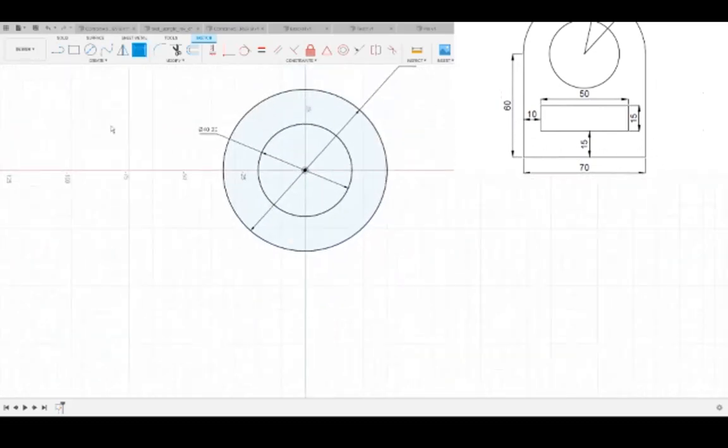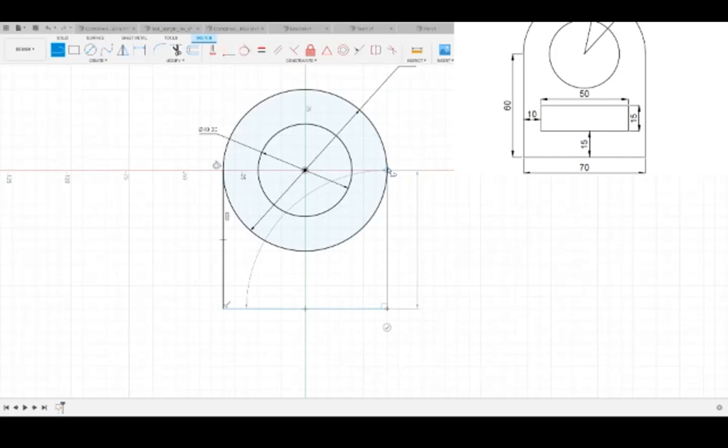So we can take a line, move that down, and although it's currently going to likely just be arbitrarily defined because often dimensions are set later, I'm setting them as close as I can to their actual dimensions, so that way when I set the constrained dimension, it's a lot easier for the model to resolve itself. Because sometimes if you set dimensions way off course, the model tends to have some strange adverse effects.